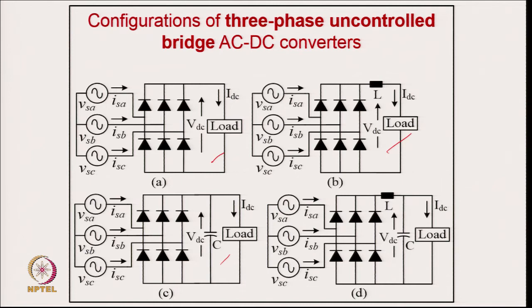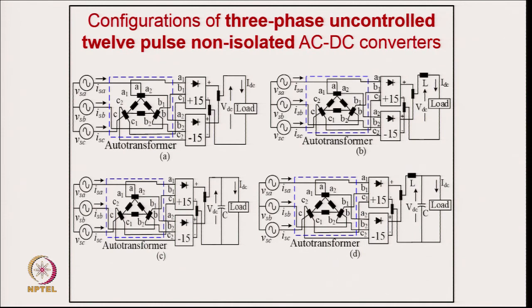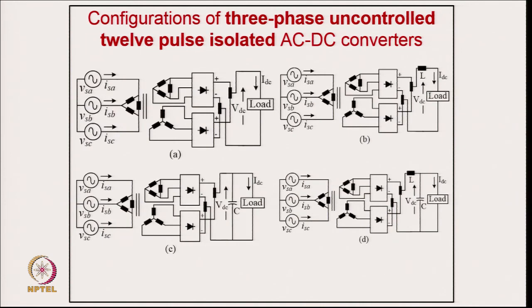So, all these conventional converters draw very high harmonic currents. And this is a 12 pulse converter with no filter, with inductive filter, capacitive filter. As you increase the number of pulses, if it is 12, the harmonics below the 11th are eliminated automatically because of the design and construction, but higher order harmonics will still be there substantially. So, you will still have around 15 to 20% THD in the supply current, which is not permitted, since you allow only less than 5% or so.